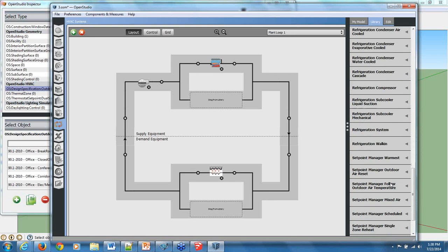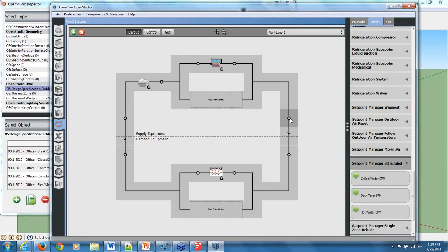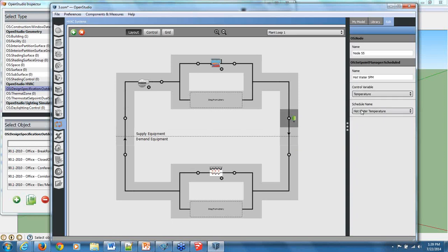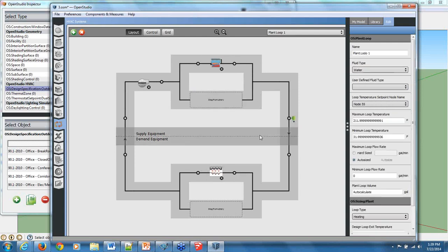system. And then finally, the last thing we need is some sort of set point controller. We can make it a simple set point controller, just a schedule controller. Say we want this boiler to deliver 180 degrees, we would make a schedule for that. We would drive it for 180 degrees anytime this equipment is enabled. It may not get there, it may not have the capacity to get there, but at least it would be the attempt to control that boiler to 180 degrees with constant flow control. So now we have what the slide called the secondary loop. This is our secondary loop.